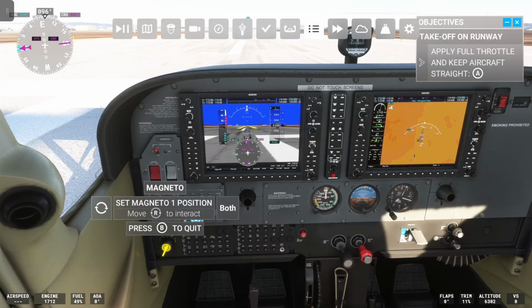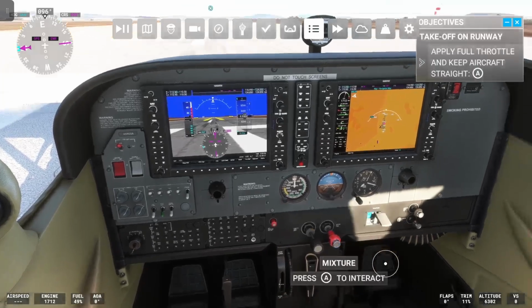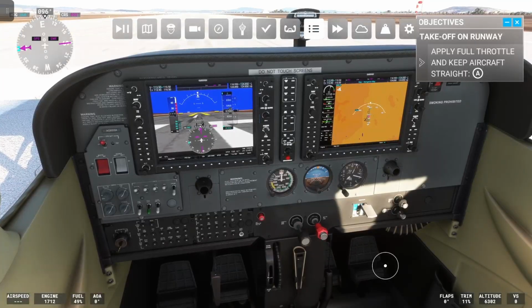But the mixture part would make this a red flag and you shouldn't fly. If the RPMs aren't shifting as you pull the mixture, that can't be normal. It's supposed to. But then again, G1000 might be a little different, but I doubt it. Under these conditions, we'll say mixture was adjusted. We moved on to magnetos, and magnetos are a check.